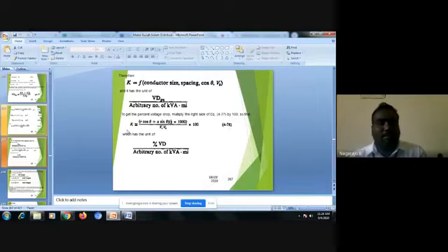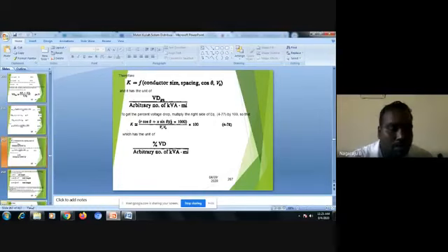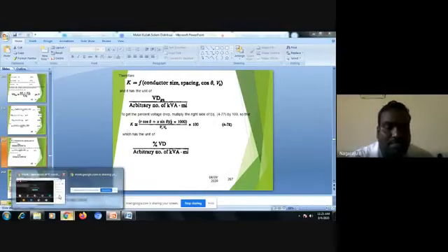To get the percentage voltage drop, for the K value purpose, again you need to multiply by the 100 value. It is also having the units of percentage of voltage drop per arbitrary number of kVAs into meters or miles. This is about the K value. Tell me if there are any doubts.